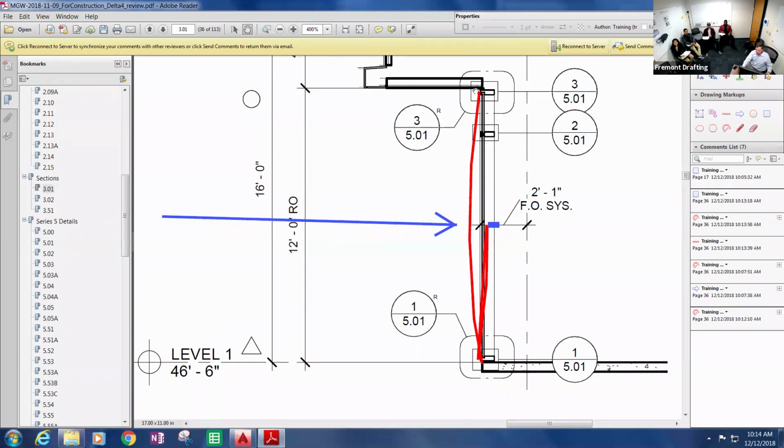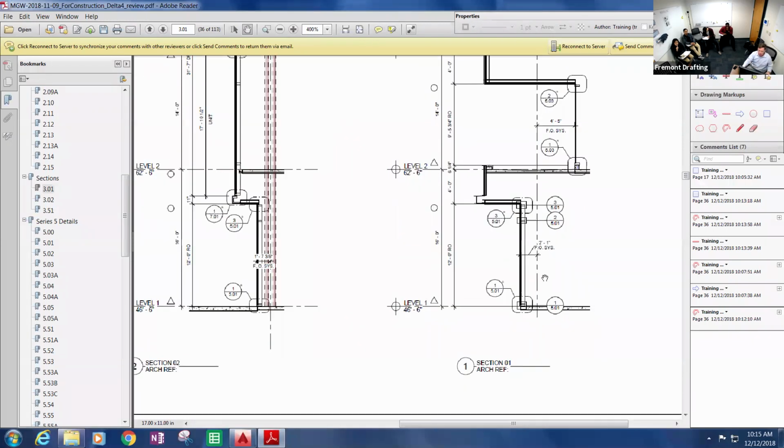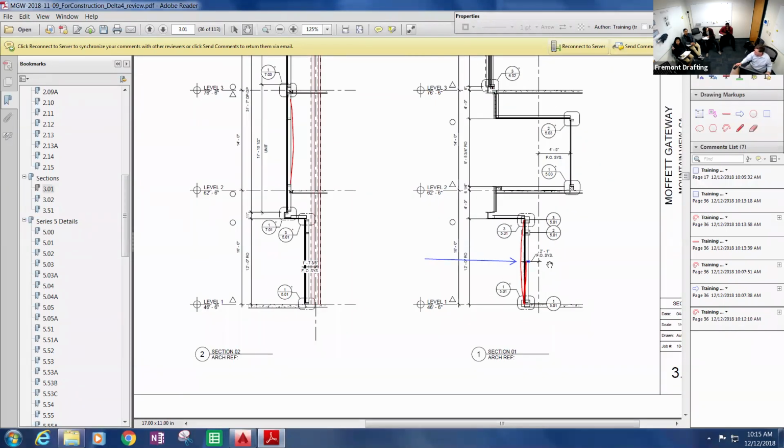So L over 175, 3/4" max for dimensions 13'6" or less. And then if I'm over 13'6" up to infinity, it's L over 240 plus 1/4" for the deflection. So if your calculation comes up that it over deflects, the result means we either have to add steel or we increase the size of the mullions. Is that right? Those are the two things.